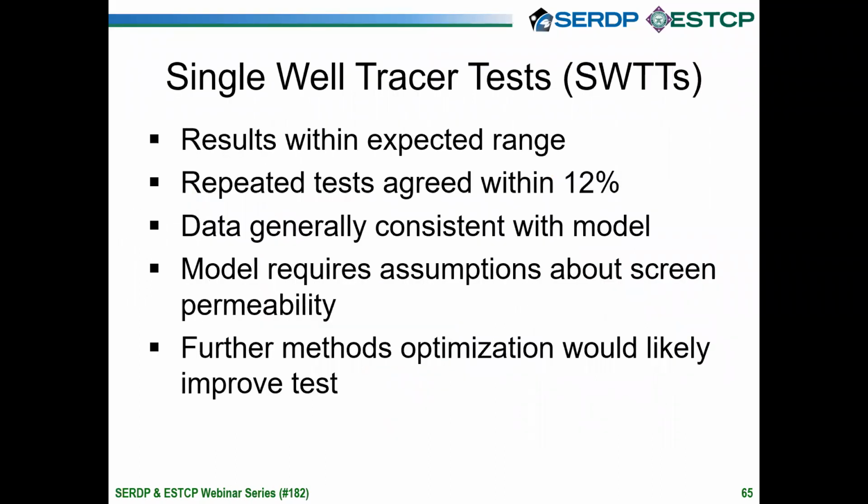The single well tracer test results were within the expected range for the site for most of the tests. We also completed a repeat test, and it agreed with the original test within about 12%. So I think the method is pretty reliable and repeatable. Also, the tracer dilution data were largely consistent with the model that was used for interpretation, so that indicates that the underlying assumptions are valid.